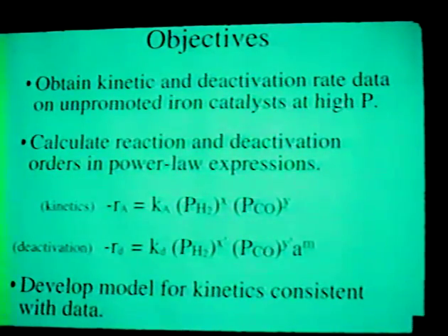And also, in terms of the deactivation expression, there's also included an activity and an order of deactivation, the M power there. This deactivation rate is simply the change in activity with time. And then lastly, develop a model for the kinetics which is consistent with the data.